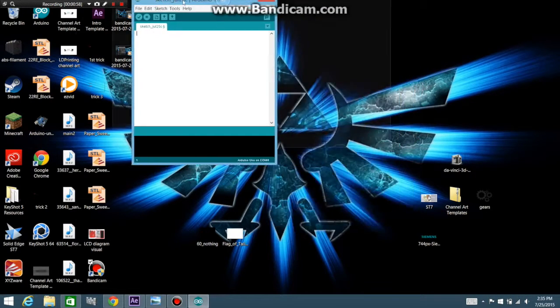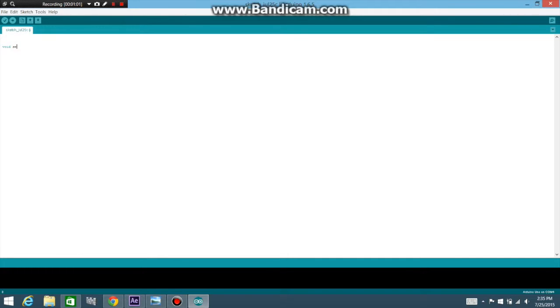So, coding. The first thing you start all Arduino programs with is the void setup. Most people should know that. Void loop isn't part of this tutorial, but you're going to need to know what it is. There are 3 main keywords that you're going to be using in every single LCD program. First one is #include liquid crystal .h, and make sure that you spell liquid crystal right, because if you don't, it won't import the right library. This tells the Arduino to include the library LiquidCrystal, which allows you to control the LCD, and you don't need a semicolon.